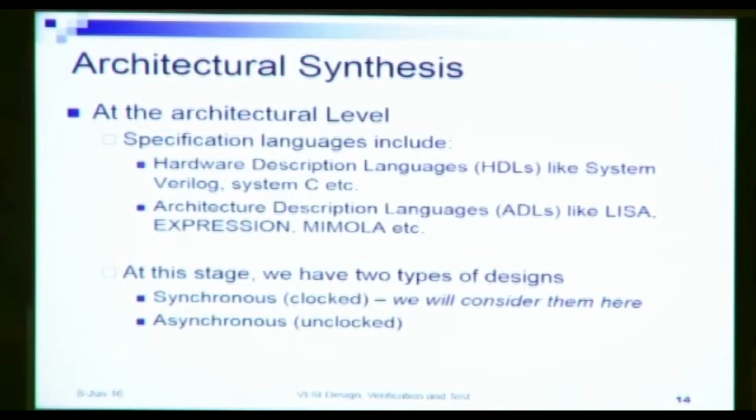At this stage of design, we can have two types of designs. We can have synchronous or clocked designs or asynchronous designs. Most of today's designs are synchronous, and it is much more mature than asynchronous designs. In the rest of this course, we'll only be taking synchronous designs into consideration. The next step is to identify hardware resources that can implement these operations.